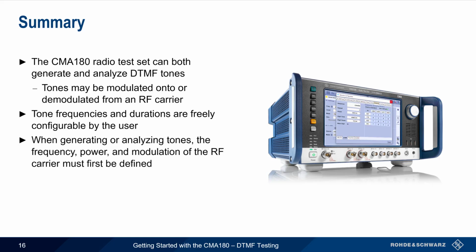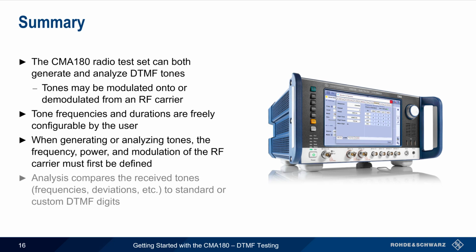Note that generation and analysis of DTMF on RF carriers requires first defining the frequency, power, and modulation type of this carrier. Analysis of received DTMF tones involves comparing the frequencies, deviation, and timings of received digits to standard or custom values. This concludes our presentation, getting started with the CMA180 DTMF testing.